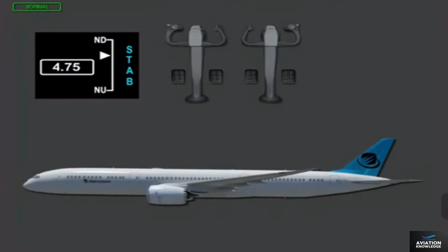If the column cutout function remains active for more than 20 seconds, the stabilizer L2-R2 ICAS advisory is displayed. The flight control system reverts to direct mode, and the uncommanded input is removed by system shutdown. Control cutout is deactivated on the ground to allow trimming nose-down stabilizer with aft column input during a touch and go.